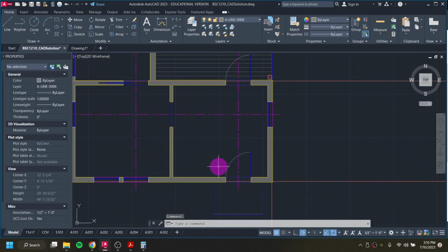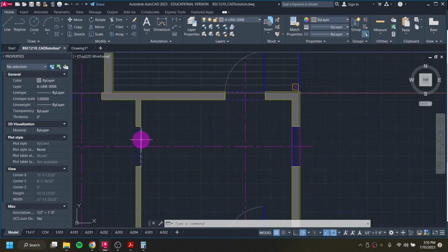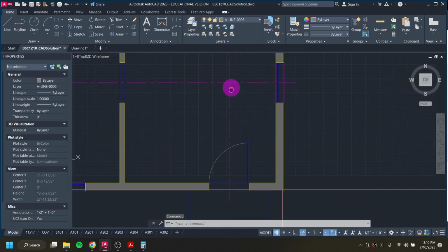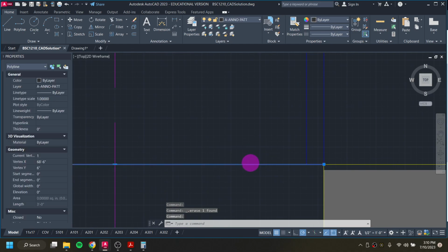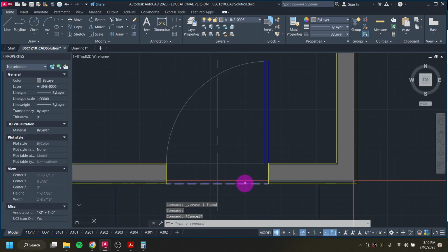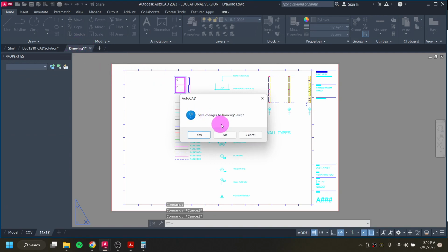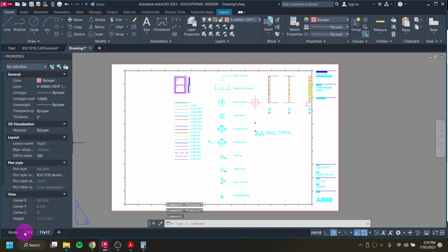So next, what we'll do is add in some of the line work related to our doors as well as our cased opening here. Within the door itself, if I delete this, you can see there is this pat line sitting underneath it, and then we also have the hidden line sitting above it. Whoops, cancel. I don't want to close out of this drawing.